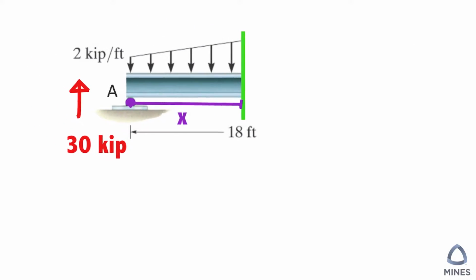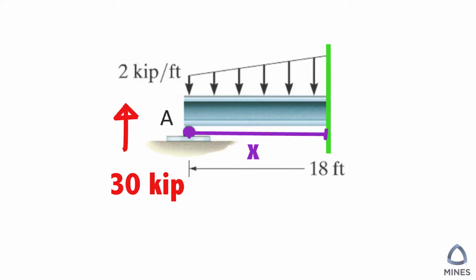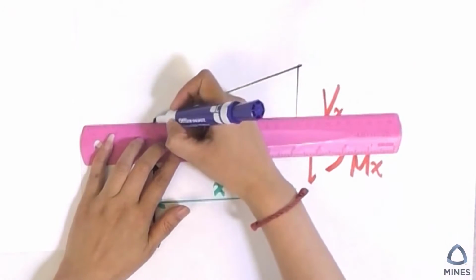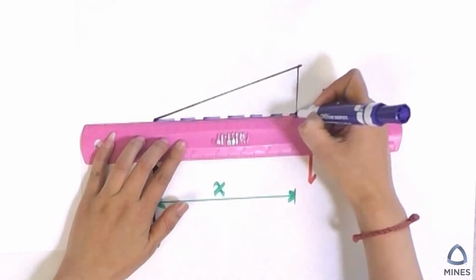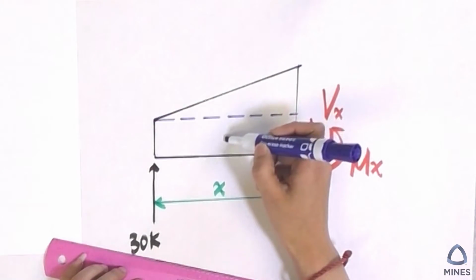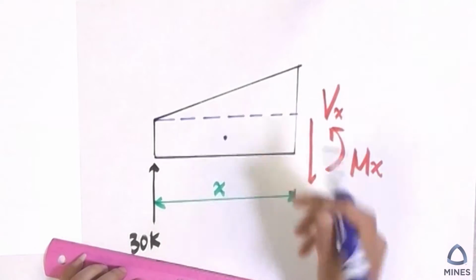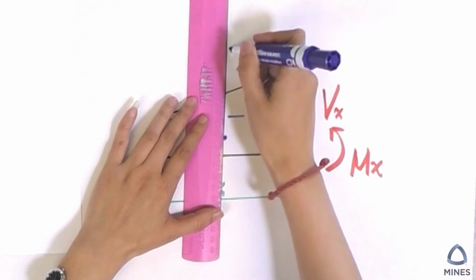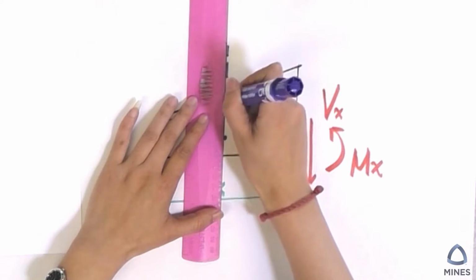What else do we see from the picture? We still have a little trapezoid. Again, we are going to simplify the load into familiar shapes, which means we cut it into a rectangle and a triangle. For the rectangle, the resultant will be acting at the center of the rectangle.